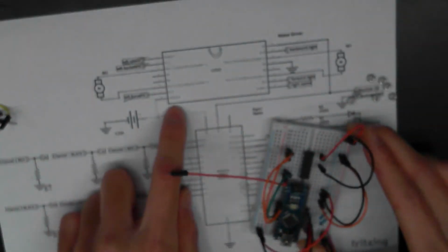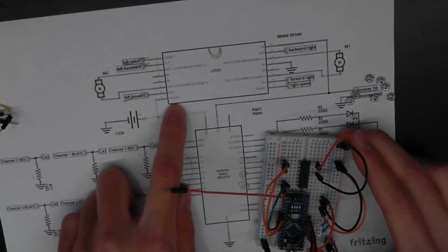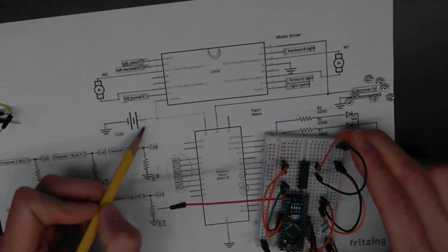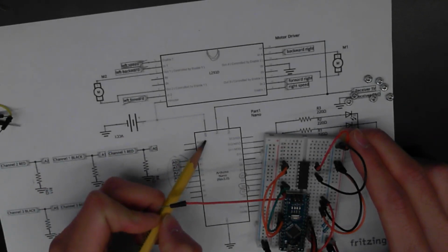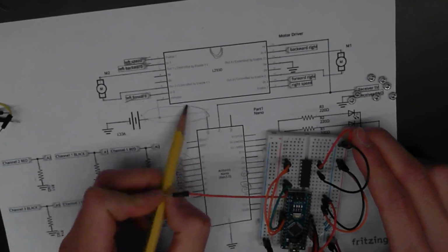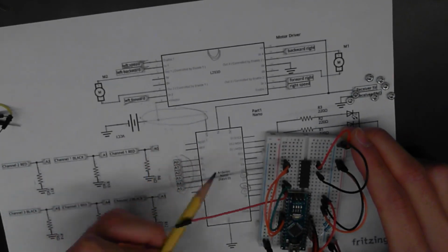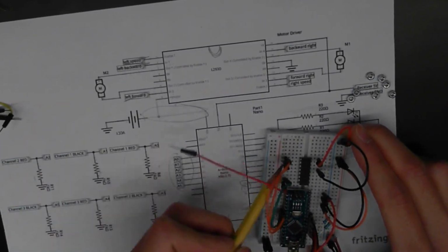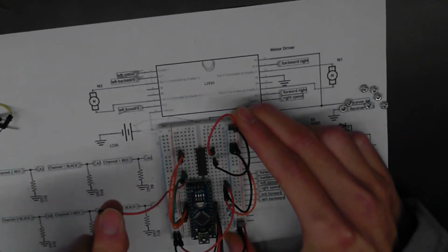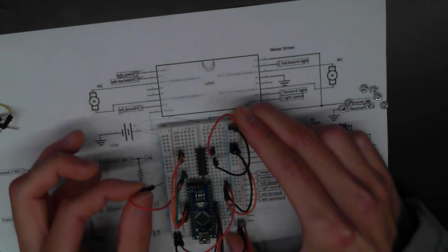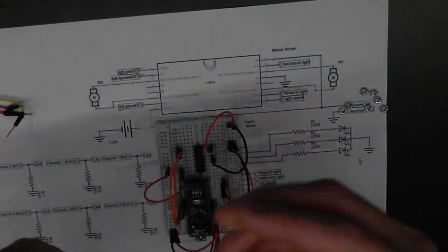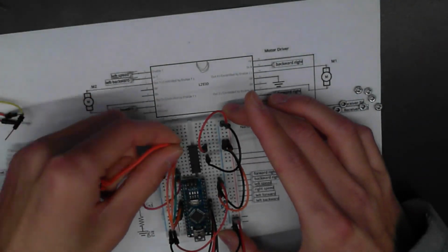And on the schematic, that's V motor. And as we can see, V motor connects to the battery and also V in of the Arduino. So on the breadboard, this junction would be the entire left column of our breadboard. So we take the red line and connect it to the right side. And I forgot to connect my battery, but my battery would go here.